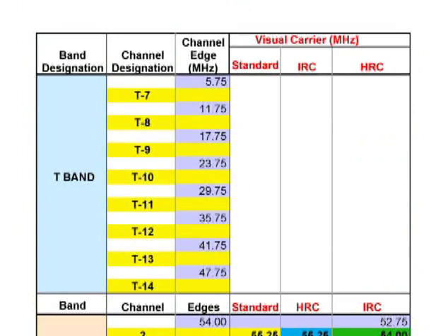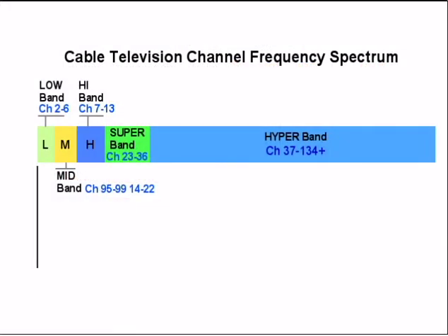Most cable companies also use the spectrum below channel 2 for upstream or reverse channel services from the home back to the cable plant. These channels are designated T7 through T14 and were originally used for transmitting channels from outlying offices or studios back to the head end. Now they're used for a variety of services, such as the upstream data from cable modems, pay-per-view signals from set-top boxes, and so on. Most cable services nowadays utilize up to channel 62, with newer systems using channels up to